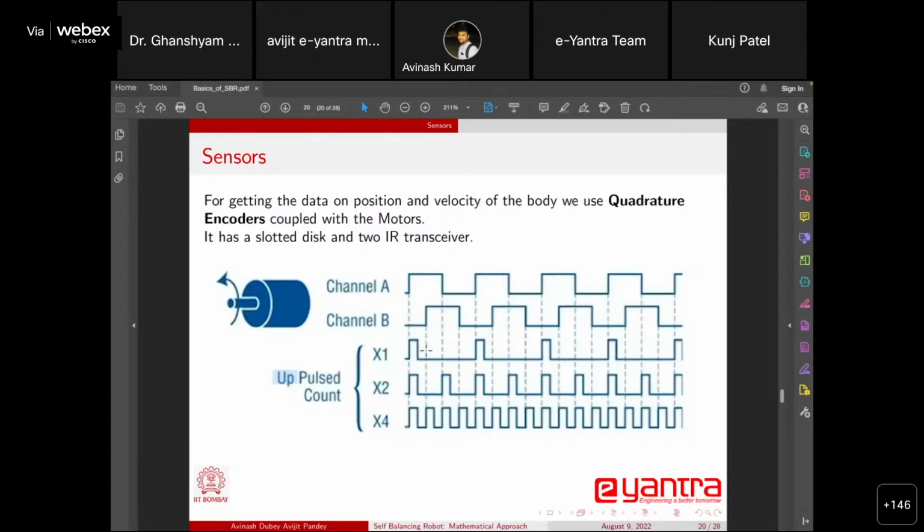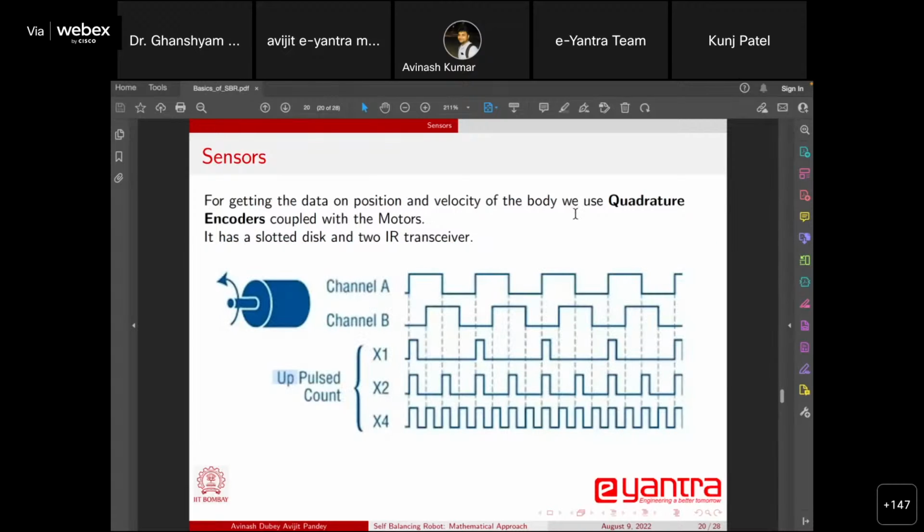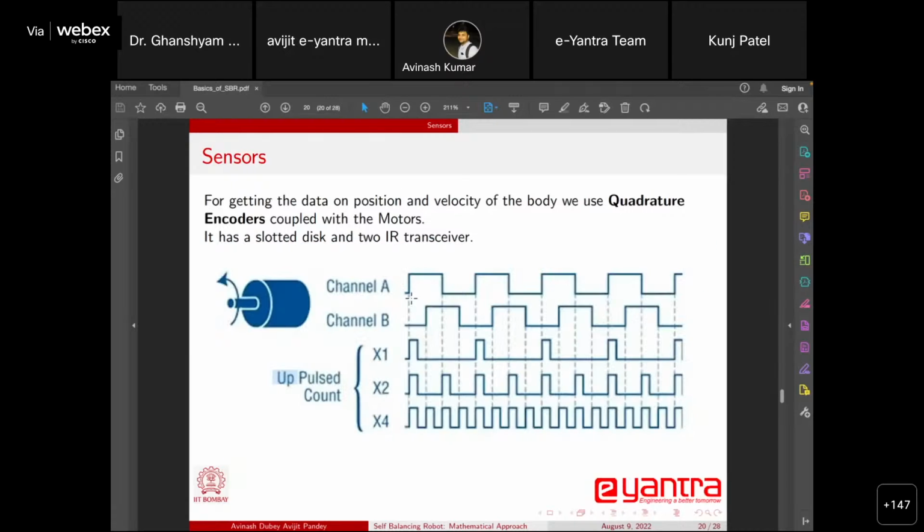Suppose you are looking at one channel only. Every time one rising edge is detected, one slot has passed. Like here, here and here, right? This section is representing the same thing. Or we can look at the same channel's rising edge and falling edge both. Within one slot, we will have two events: a rising edge and a falling edge.